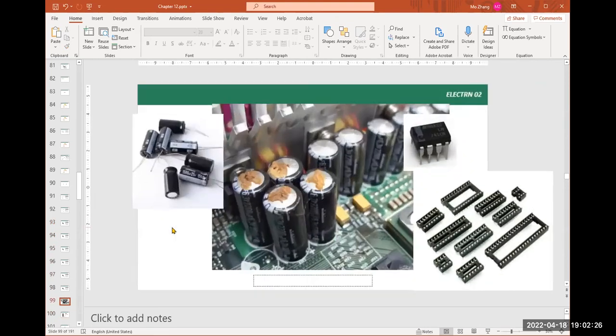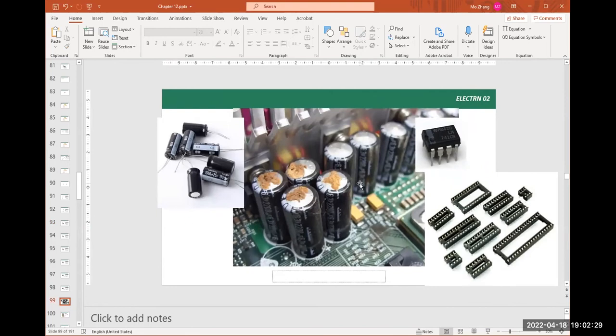Oh, here, that's a good picture. So here it shows the capacitors are all exploded or broken. These four with the material residuals on top of the cap, that's even worse. The things come out from the stomach and then leave from the head, from the mouth. No good. And those are bad also. This capacitor has a round head. If the head is not flat, in this case round, that means it's bad, it's broken. They cannot be used anymore.